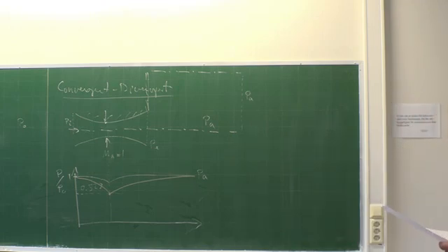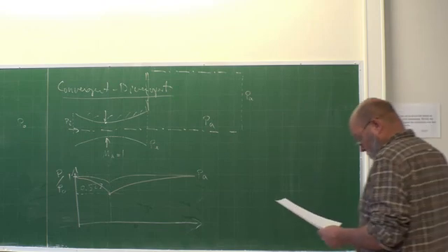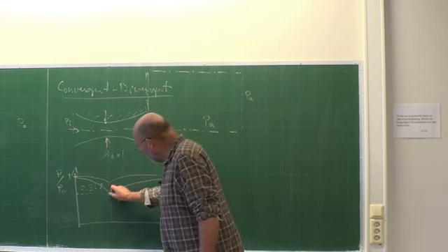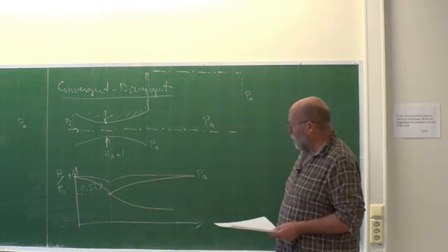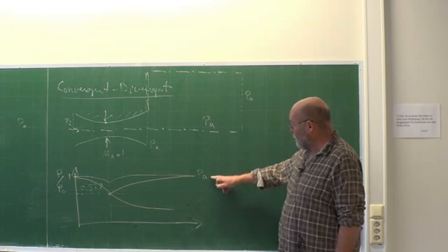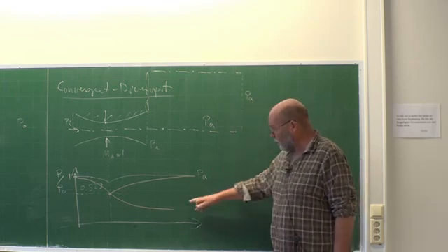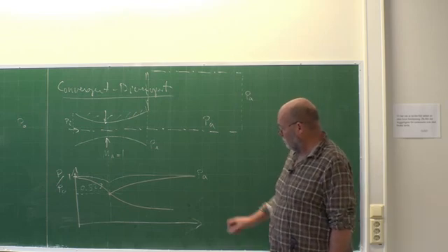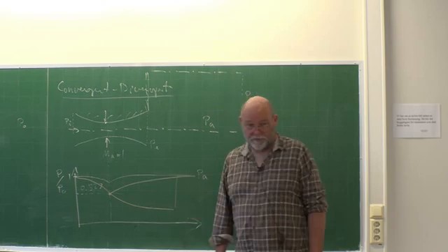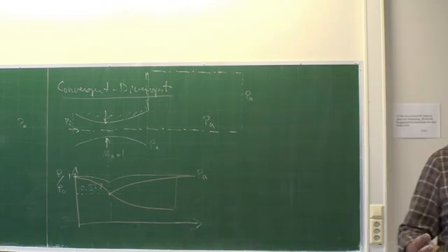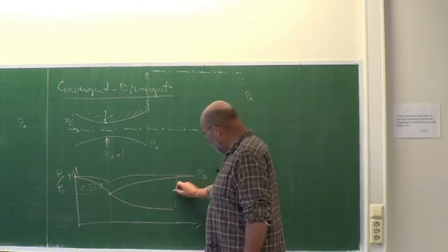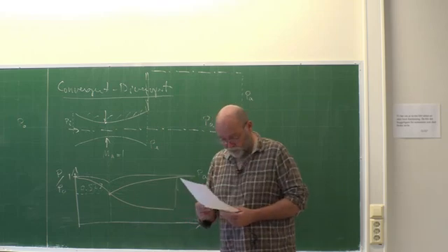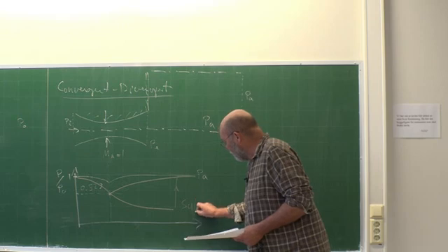But then, if we increase the driving force even further, then all of a sudden we can have a solution looking something like this. But it has to meet this surrounding pressure here somewhere. There you have it. It has to do something. And the only way it can do that is through a shock. So yes, then you will have a shock wave. Then all of a sudden a jump, then you call it supersonic.